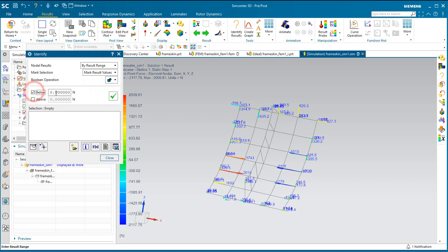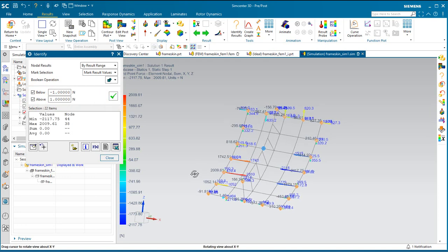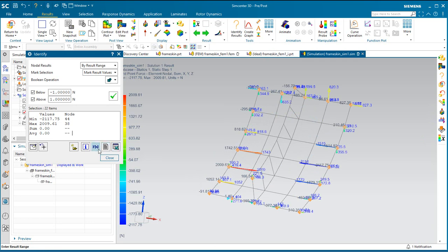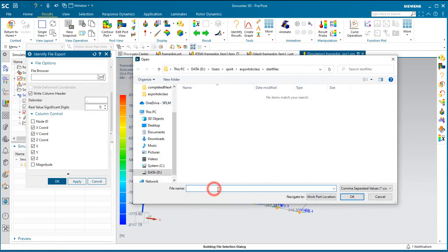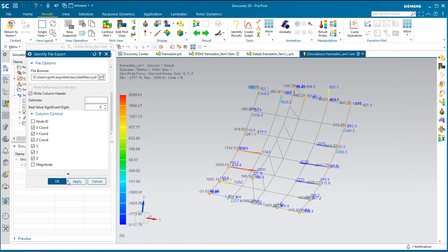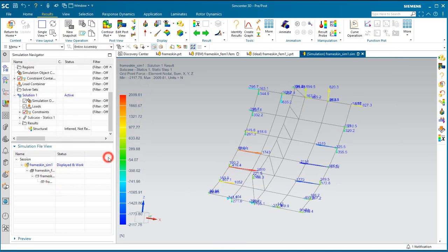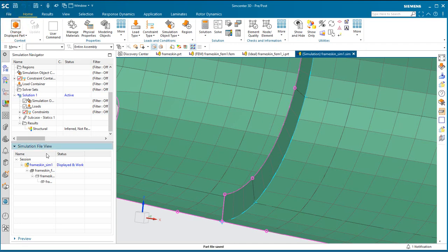Alright, so there's a number of ways that we can grab those nodes around the perimeter. Basically, they're all the non-zero results. Everywhere else, the sum of the grid point forces is going to be 0 along the rest of the model, except on the perimeter, so I'll go for those non-zero results. And I want to write them out to a file, the XYZ location and the XYZ force. We'll use a comma delimiter. We'll write it out to a file called XYZF. And we'll use that in just a moment for our fine grid breakout model.